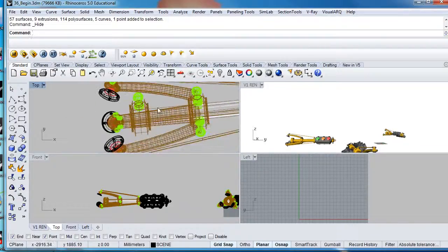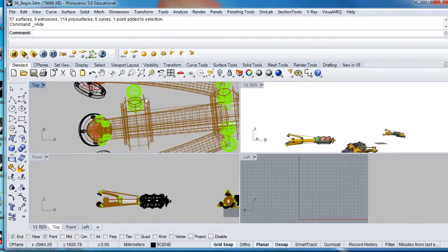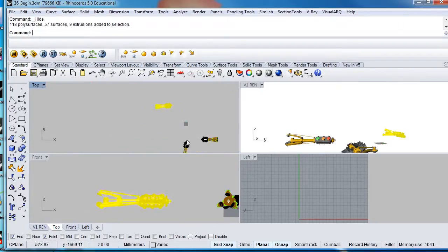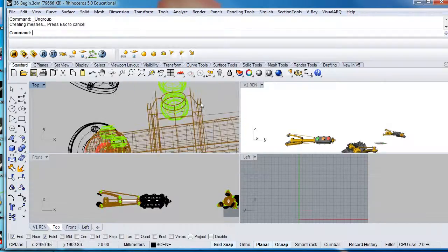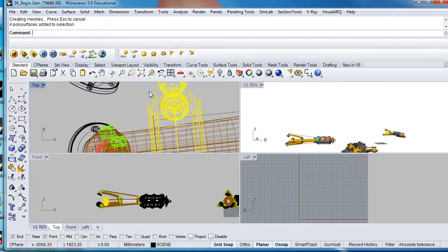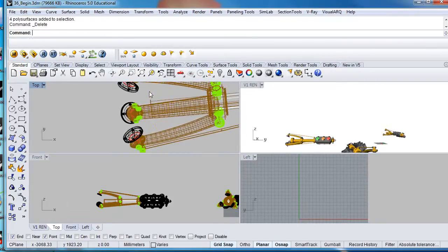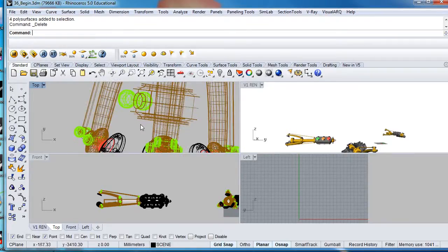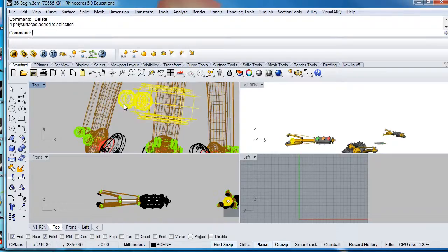needs to be refined. In this particular case, we want to remove the lower ring there, so we're just quickly going to select all three designs, ungroup them, there we go, zoom back in, grab that element by itself, press delete because it's no longer needed in that configuration, zoom back in on the next one, scroll from right to left to select that item.